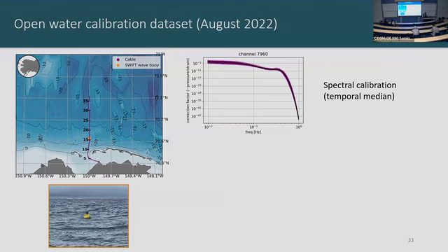Okay, stepping backwards now, the way that we did this was with empirical calibration, where for each channel we took that whole week of data and at each point in time divided the spectra from the buoy by the spectra of the strain from the cable. So this is just that ratio of these two spectra. The purple lines are from each point in time over that period, and then the black line is the median of that, which we use as our correction factor to apply to the full data set as a consistent correction factor.